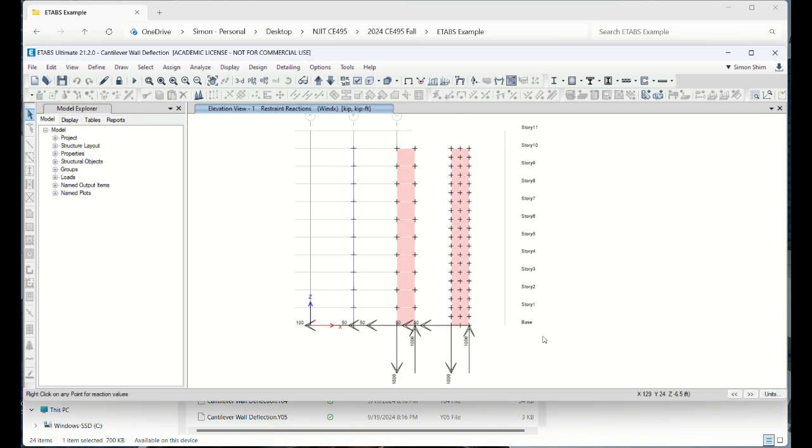And then if you are interested to look at the shear force, how can you check? So shear force and moment are more likely internal forces, right? Our 100 kips is an external force, but internal forces apply that this wall section is experiencing inside internally. So these we call member forces, right? External force 100 kips generating these internal forces. We happen to call it axial force, either compression and tension, shear force, right? And then bending moment. Those are our terminologies, but those are all internal forces.